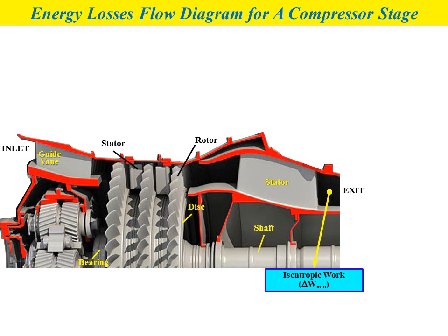We already learned that for the work that we need to supply to the compressor, for ideal case where we ignore all the losses, we will consider the energy or work as the isentropic work, delta W minimum, where this value represents the ideal work to obtain the stage rise in the compressor, delta P, where delta P equals pressure at the exit minus pressure at the inlet.